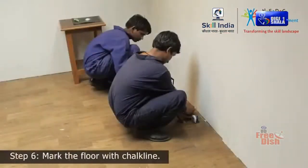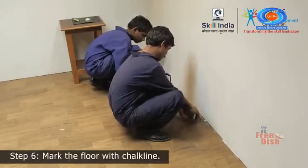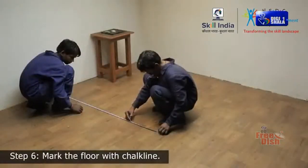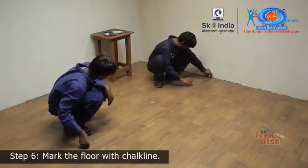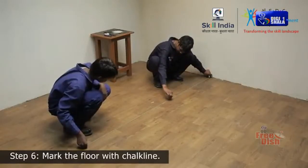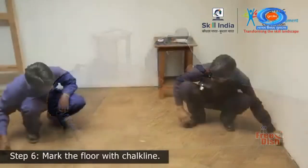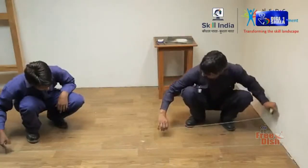Step 6. Mark the floor with chalk line. Measure the distance where you want your partition to stand up from the wall and put a temporary mark on the floor. Hold a chalk line string at one end of the mark and ask a helper to hold the string directly over the other mark. The string must be stretched tightly. Lift and snap the string from the middle. This will give you a straight line, a reference for your partition frame to stand.